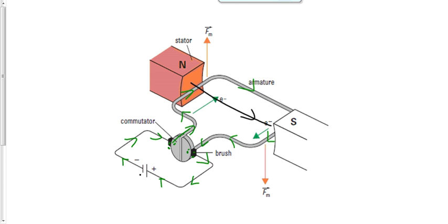All right, so we get how these electrons go around this circuit, this armature, but it doesn't tell us anything about how this armature spins, how this electric motor will spin around to cause the drill bit to drill into a piece of wood or to cause the mixmaster beaters to beat the cookie dough. So how does that work? Well, we have an electric current right now going through a magnetic field, right? We see that there's the one right here going through the magnetic field that's kind of into the page, and then there's the one right here that's kind of out of the page.